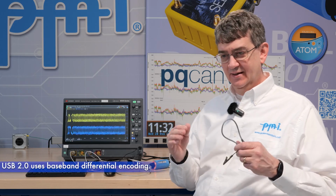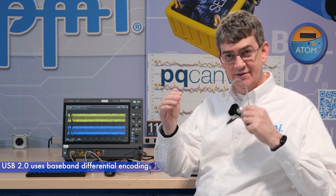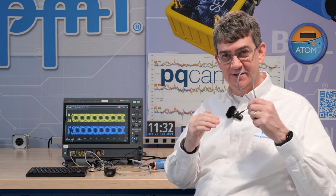Today we're going to be testing the USB port of the Bolt. USB is an interesting protocol in that it's extremely high speed, but the physical layer protocol is very simple. It's a differential encoding. The data is encoded with two data lines, a D plus and a D minus line, and it's differential. One goes high, one goes low, that's a 1, and when they swap, that's a 0.